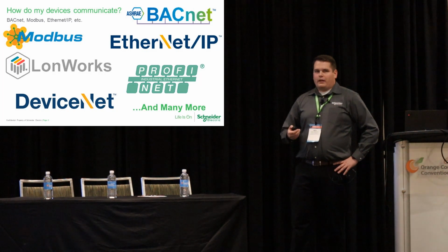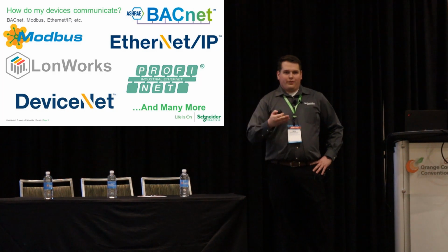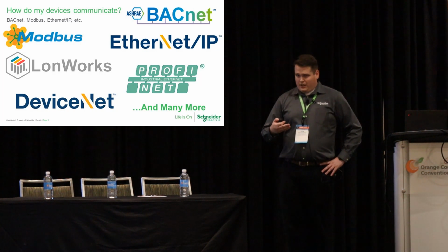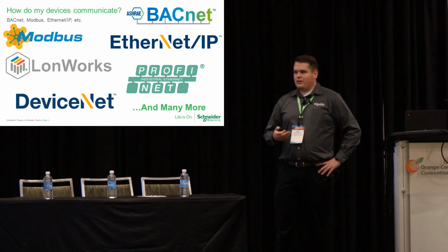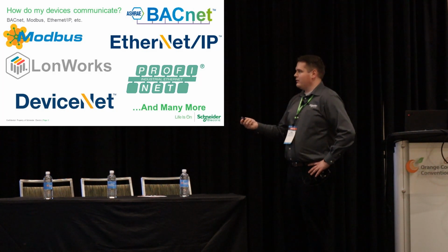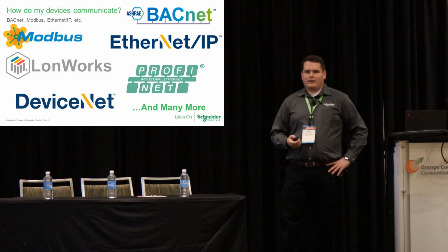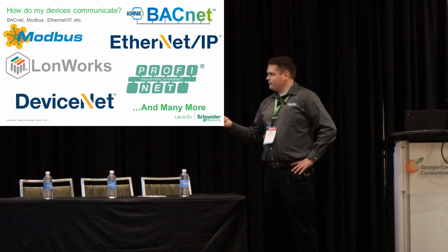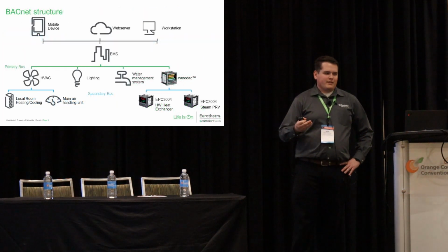A lot of companies will make gateways. If you have a Modbus device, you need to communicate on BACnet, or Ethernet IP, you need to bring that into a BACnet system like a Schneider Electric EcoStruxure, Johnson Controls Metasys, any system like that that's looking at a whole building automation is most of the time a BACnet system. And there are many more protocols. Some devices have their own custom built that they've written that they use, and then you've got to kind of decode what they've done to get all the info out. Mostly I'll focus on BACnet in this just because that's the standard in this industry.